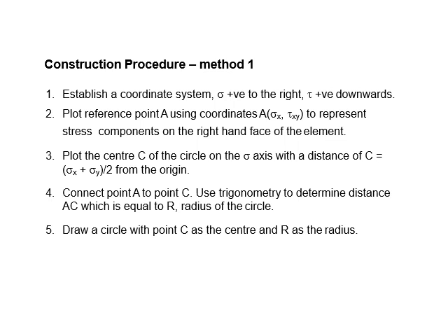So you need to determine where the axes are, right? For the horizontal axis, or the normal stress, that's not a problem, just put it in the center of your graph paper. But for the vertical axis, which represents tau, the shear stress, you have to be careful, because you need to determine whether the graph is going to be on the right of the axis, like our previous example.